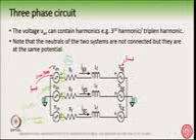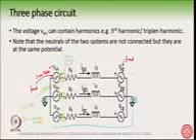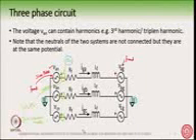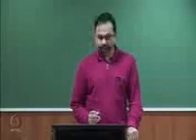If I had connected this point to this point, that is a three-phase 4-wire system, then the harmonics will start to flow. The third harmonic will start to flow, because it will get a path. Otherwise, in most cases, this is not there. In a three-phase 3-wire system, it is not there. So the harmonic voltages will appear, but they cannot inject a current into the system.